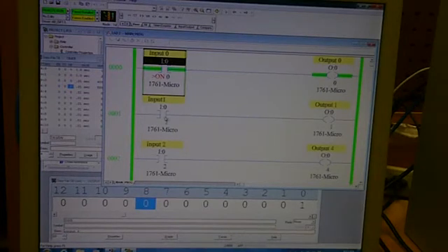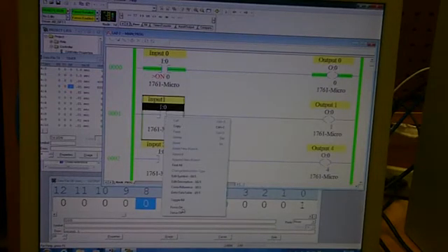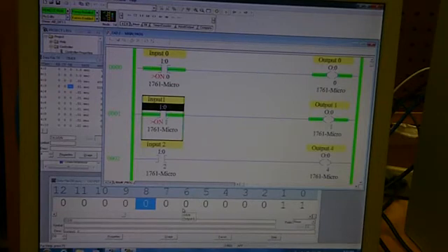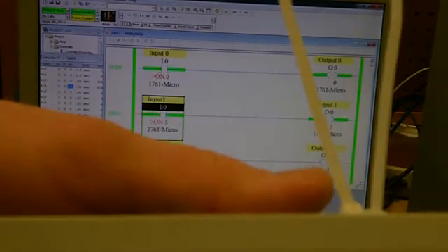All right, so now we're going to do the same thing, and you may have heard the click, because this is a relay system. I'm going to force on input 1, and see if we can hear the click. So we heard the click. Whether or not the video heard the click or not, that's a different issue. So now input 1's on. I'm showing that the output's on.